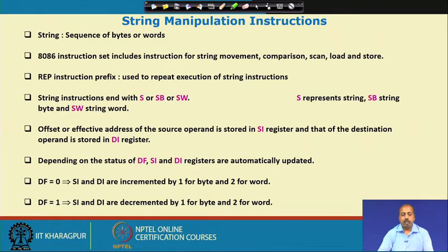And then we have got the string manipulation instructions. A string is nothing but a sequence of bytes or words. So, we can think of it as a sequence of bytes stored in the memory. The 8086 instruction set includes instructions for string movement, comparison, scan, load and store. There is a REP instruction prefix, which is used to repeat the string instruction.